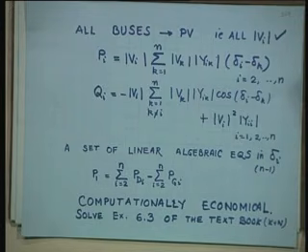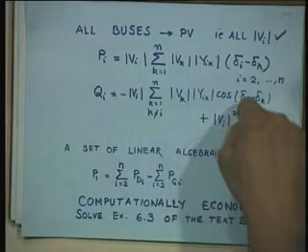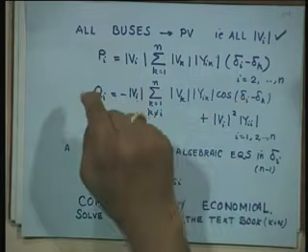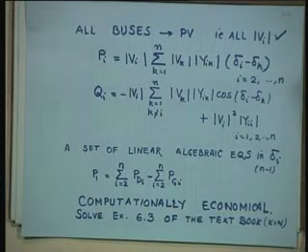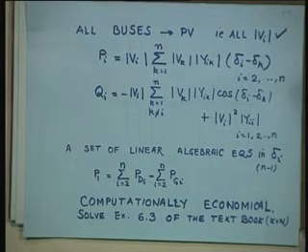And this equation will give you the values of delta, which you then substitute here to get the value of Q. So, it is a set of linear algebraic equations in delta only; voltages are not unknowns, and hence we can solve them by ordinary closed form solution, Cramer's rule, those determinants and all those things. And once we know that,